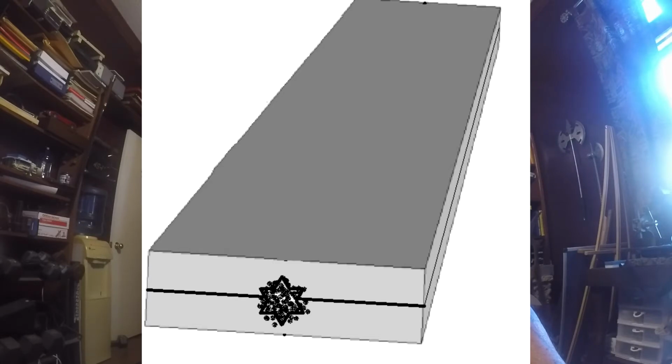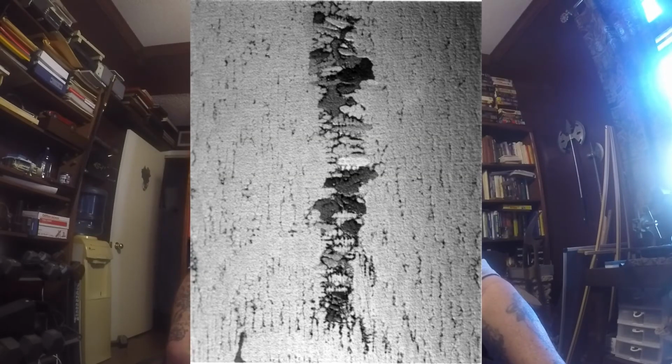And along the length of this slab, in the center, is going to be some shrinkage. Here's a picture that shows that type of shrinkage. On the right hand side of the picture, nobody polished it down to where you could see the individual crystals. You can see the saw marks, but if you ignore those, you can see where the crystals grew from the right hand side to the left hand side, and at the bottom, how dendrites were growing straight up.